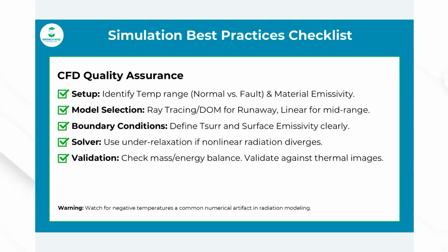If you do end up seeing a negative temperature problem, check your time step, try reducing it, check your Courant number, try reducing it. And for the most part, please do check your boundary conditions. There have been instances where I myself have done it, where I think 300 Kelvin, I might put 273, or just by habit, if I do Celsius versus Kelvin, I might mess up the whole thing as well.